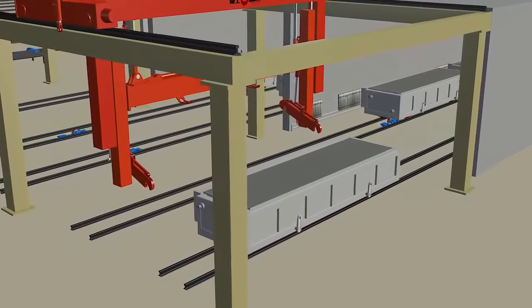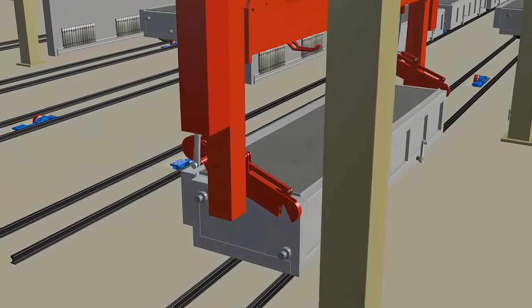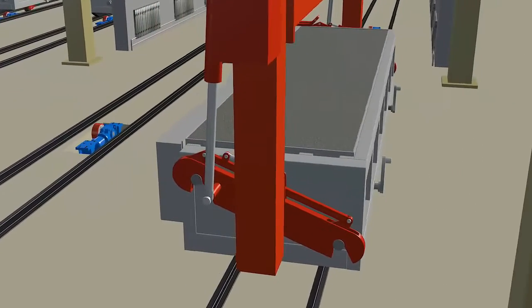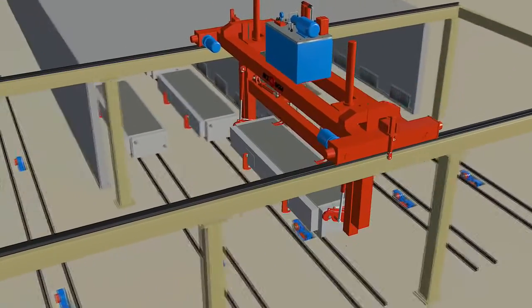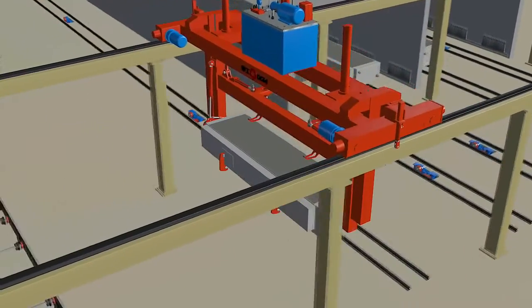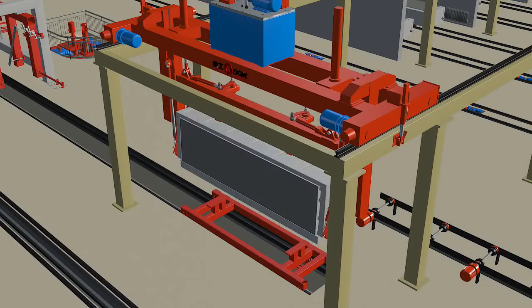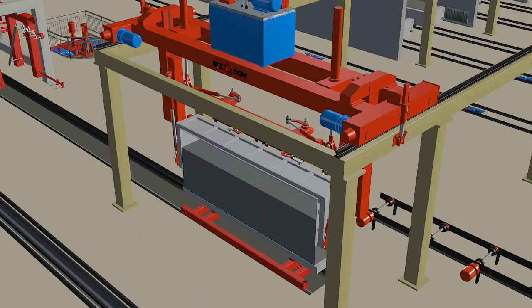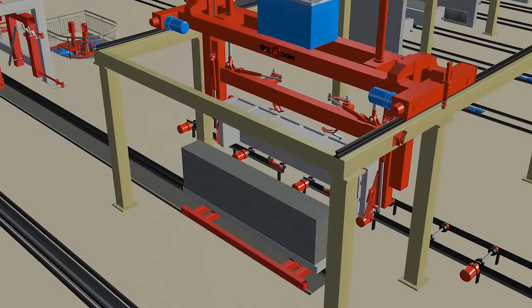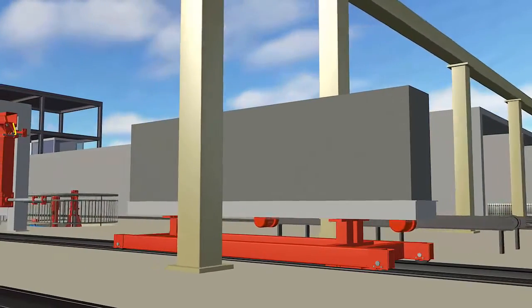The mold with the casting cake is transported to the cutting zone by a turning hanger with automatic positioning, and put onto the loading car after 90-degree overturning. Then the manipulator separates the cake from the mold. After demolding, the cakes are being cut in the cutting machine.